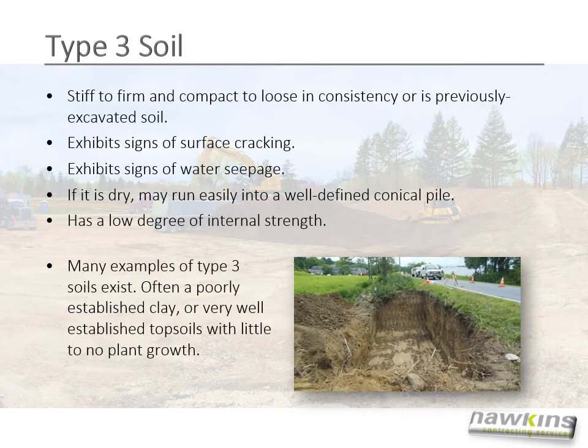Type 3 soils are stiff to firm and compact to loose in consistency, or it's previously excavated soil. It exhibits signs of surface cracking. It exhibits signs of water seepage. If it is dry, it may run easily into a well-defined conical pile, and type 3 soils have a low degree of internal strength. Many examples of type 3 soils exist. They are often a type of clay that is not well established to be considered a type 2, or very well established topsoils with little to no plant growth.